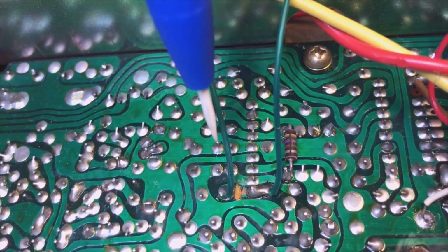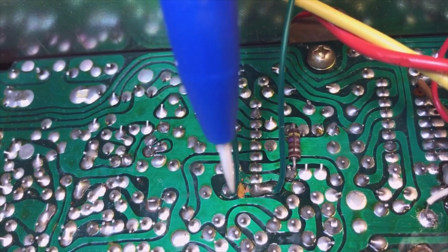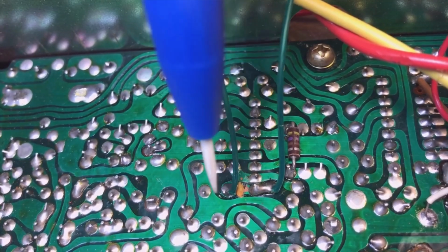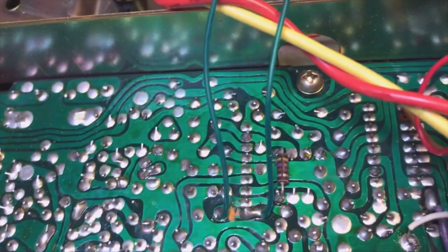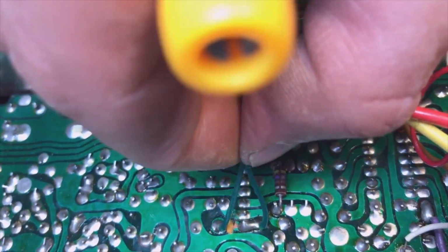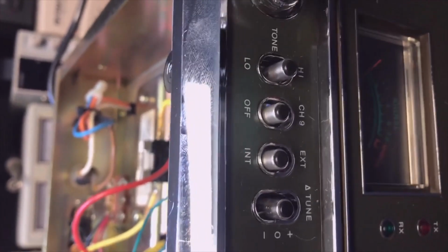In normal operation, we just want this trace to be closed again, so we do this with a switch. We connect for normal use, and when it's open we need to put the trimmer in. You can use an old switch that you don't use, usually the internal/external speaker switch, because you use it one way and you're not going to switch over.